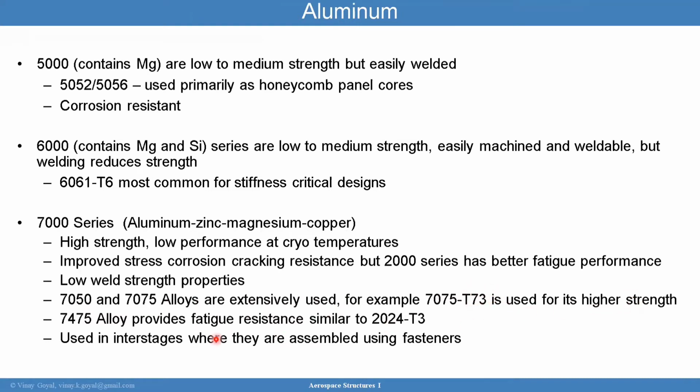The 7475 gives you fatigue resistance similar to the 2024 series, and these tend to be used in interstages, where you're assembling using fasteners.